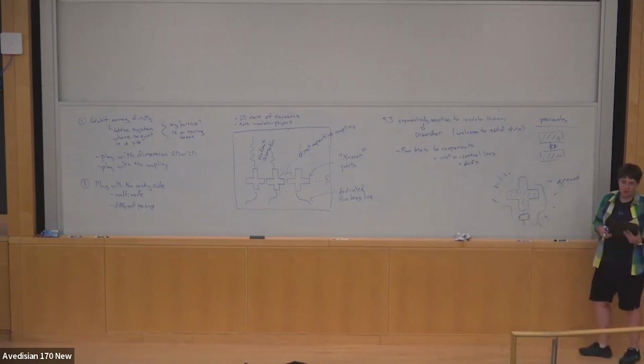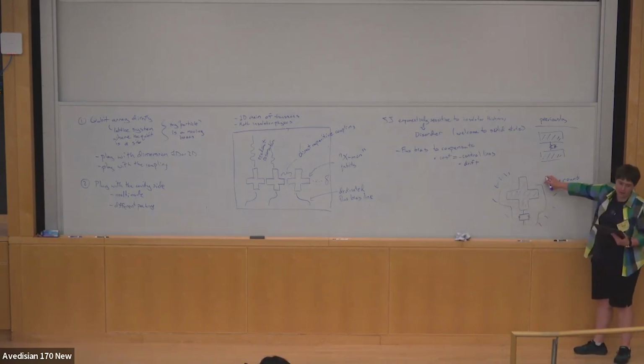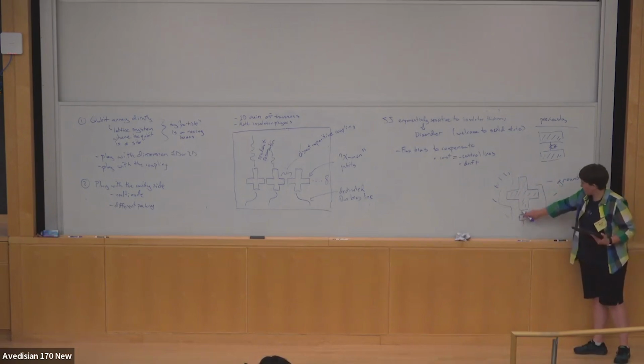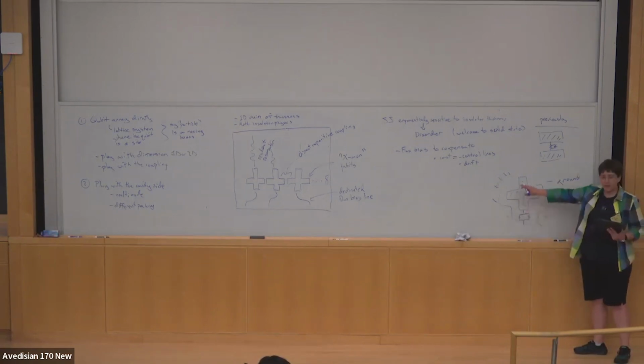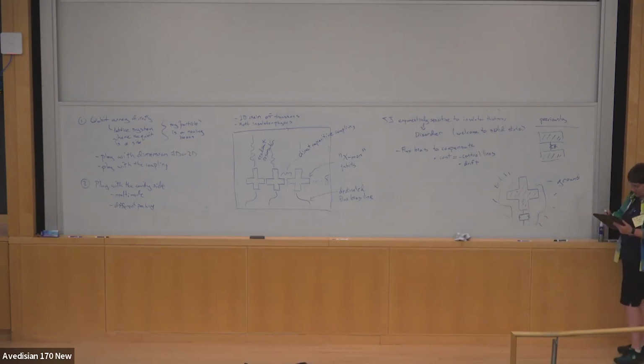And so the XMON lives by the capacitance between this piece and ground, and then the Josephson junctions, or the squid, connect that one floating piece of metal to the ground plane. XMON is sort of John Martinis Google style.